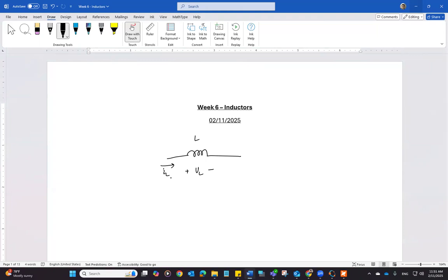If you have an inductor in an AC circuit, since the AC voltage and current are always changing, the magnetic flux around that inductor will always be changing. So you always have a voltage across the inductor, and its polarity keeps changing because the current and magnetic flux are changing. The energy is stored in the inductor. Sometimes it will be stored, sometimes it will be supplied, based upon the cycle that your circuit is going through.